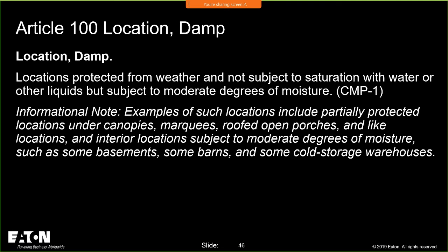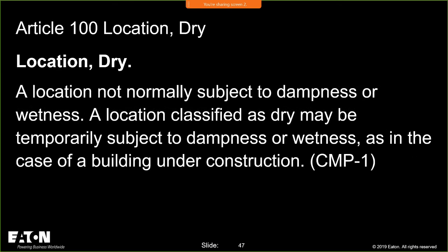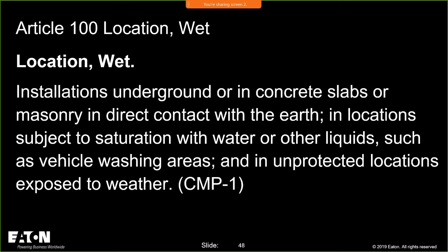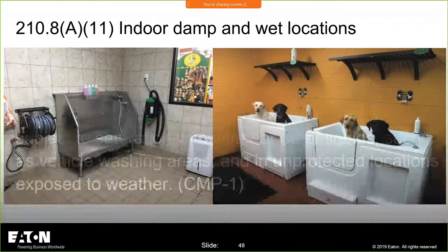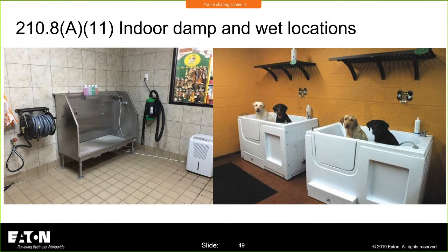Okay, damp locations. You have to understand what a damp location is. Look at the definitions. You have to understand what a dry location is and what a wet location is. I'm not here to help you understand that. All I know is we have to protect those pooches. They deserve it just like everybody else deserves it. And these areas may not be in an area that's currently requiring GFCI protection.